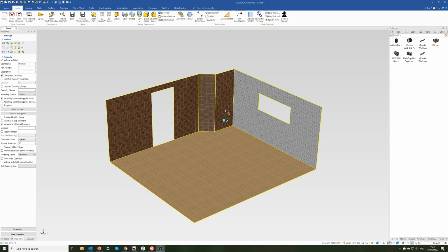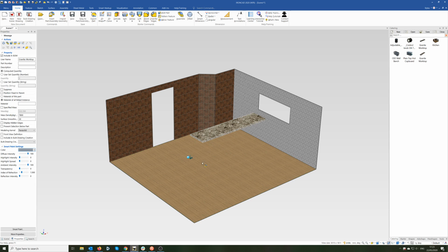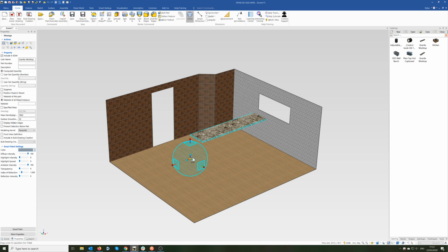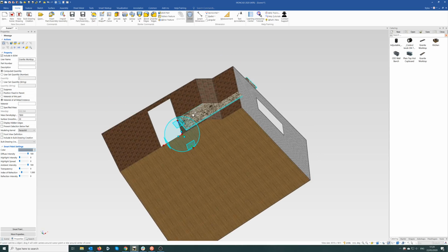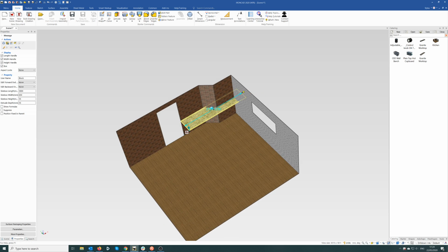What I'm going to do is put some granite worktop across there, and I'm going to show you this is an odd shape, and I just wanted to give an idea how we would do that. So I've saved a standard granite size. I'm going to drag and drop my granite into that point there, and move it to that point, and there you can see I've got it there. I think it's about right. Let's just take that and drop the size down a bit to about there.